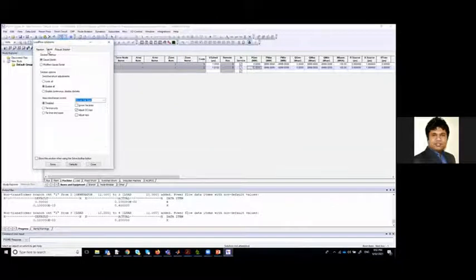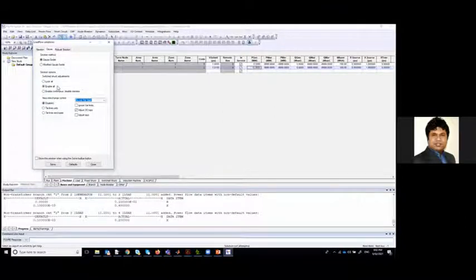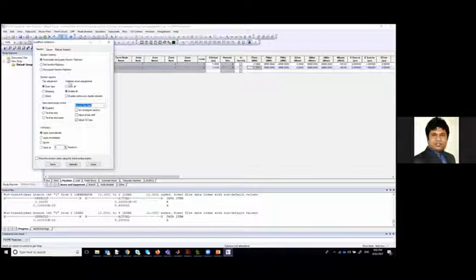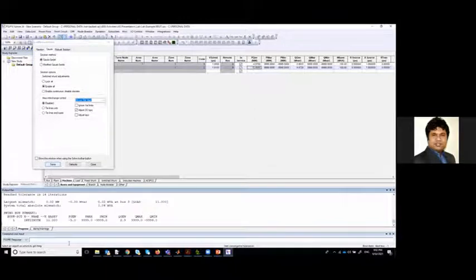Let's use the Gauss-Seidel method or the Newton-Raphson method. These are the methods we most commonly use, but the difference is the number of iterations. Gauss-Seidel will take more iterations, around more than 10. But Newton-Raphson will take only 3-4 iterations to solve the problem. Let's solve it with the Gauss-Seidel method.